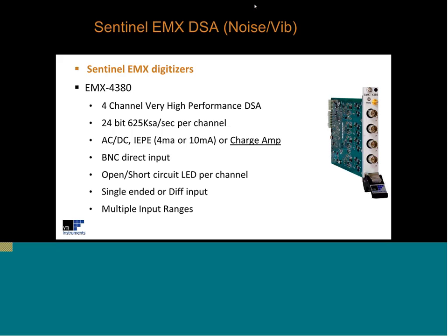And here, this gives our users the ability to have one hardware configuration, and through software can configure that card to take voltage inputs, IEPE transducers, or charge inputs. Everything's BNC input. You do have the open and short circuit LED again on this card. And all of these cards do support TEDS, by the way.